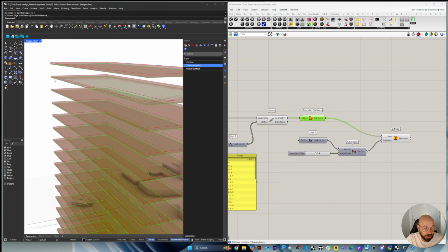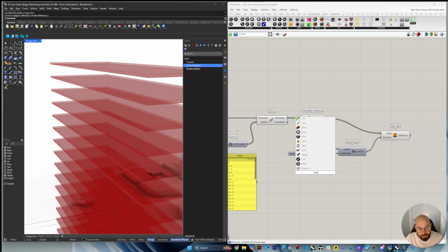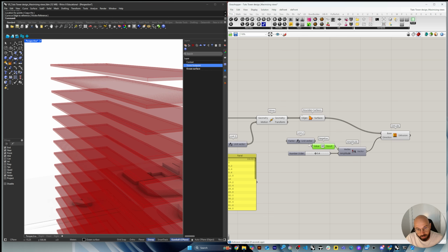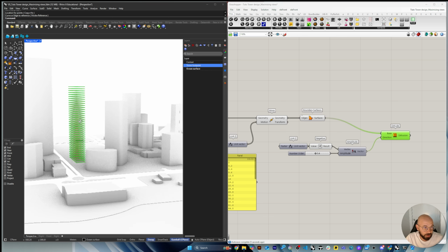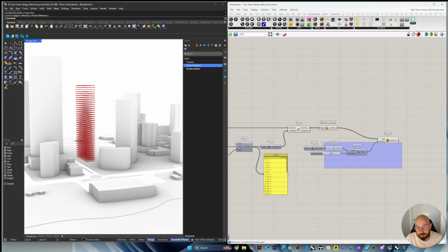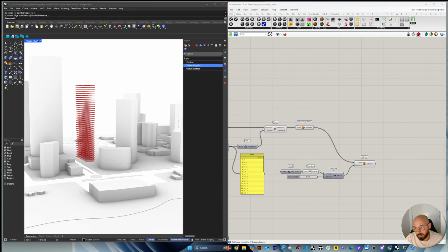So I like the slab to be towards the bottom, underneath, and we have that surface always at the top. It helps with apartments. If you deal with apartments, if you start populating those areas to put it eventually into Rhino, it helps to have it as the top floor. So here we're gonna do negative, and negative will actually help us put it towards the bottom. Okay, and now you've got the tower here. So that's how you can get your slab.